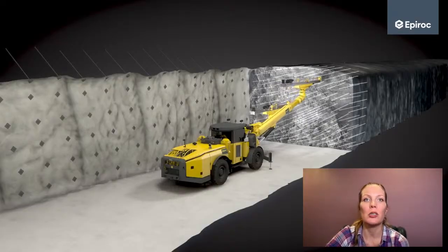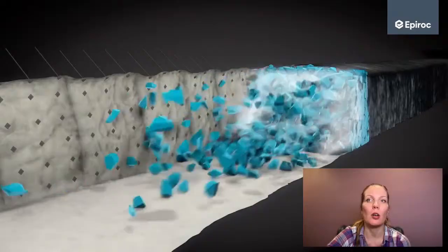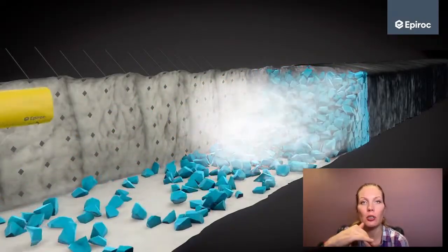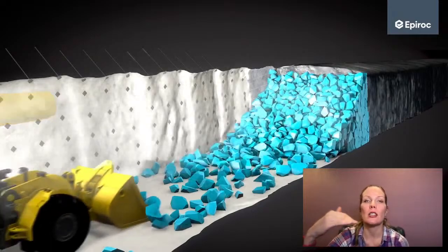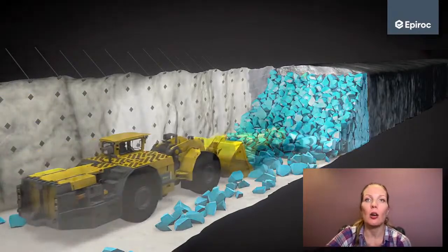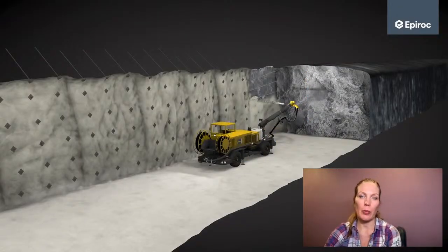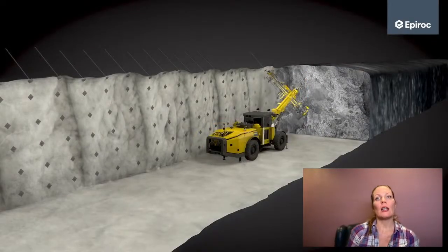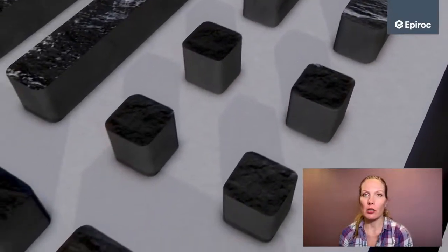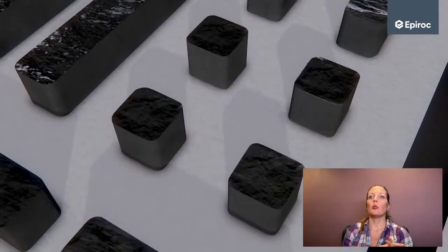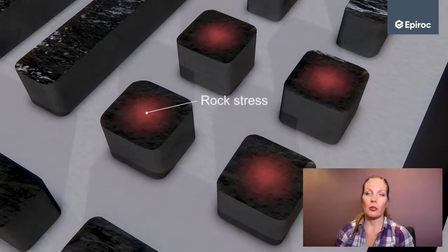Two adjacent rooms cannot be taken without a pillar between them. A cell cannot be mined if doing so breaks the ventilation circuit. And the rooms connected to the same narrow drifts cannot be worked at the same time. Scheduling operates on this dependency graph, assigning time windows to optimized stopes panel by panel. Within the set of geomechanically permissible options, economic indicators help determine priority. Cells that improve metal output in a given period or help close a tonnage gap move forward first.